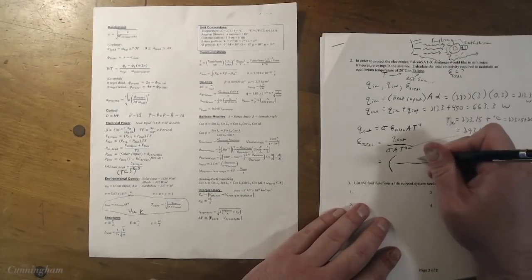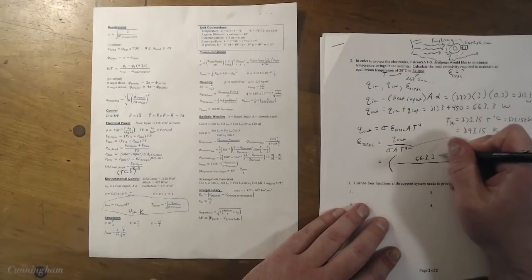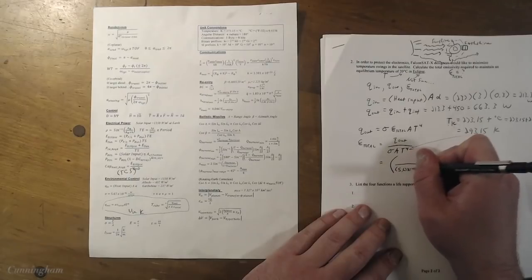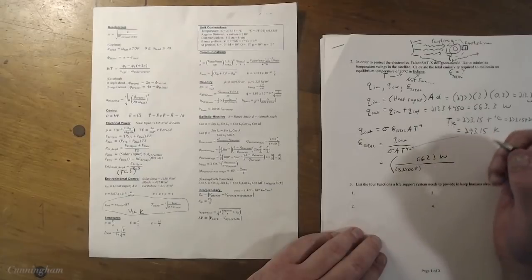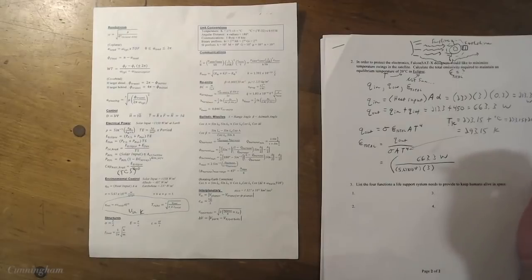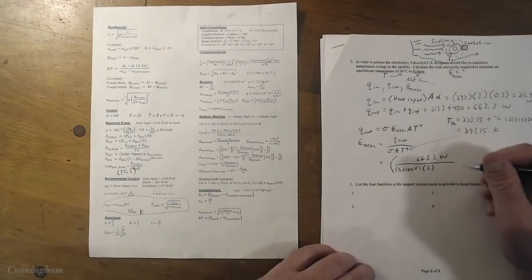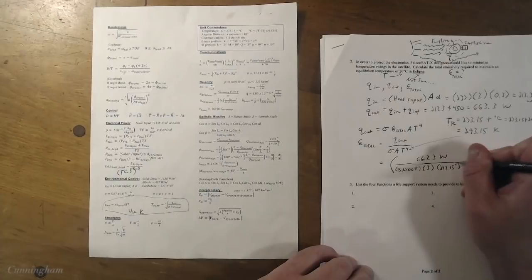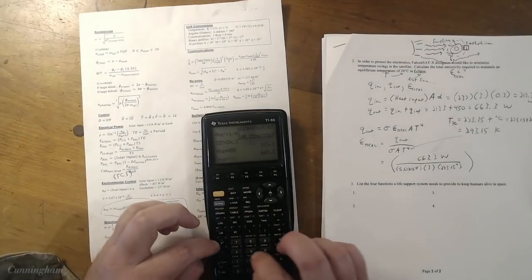Q out, we discovered in eclipse, was much lower, obviously, because we're not taking as much heat in. So over that, and then 5.67 times 10 to the -8, with units of watts per meter squared Kelvin to the fourth. The area is still 3 meters squared, the area of one side that's taking all the heat. And then T to the fourth, not 20 degrees Celsius, but 20 degrees Celsius in Kelvin, so 293.15 raised to the 4th power. Should give us something not crazy, hopefully.